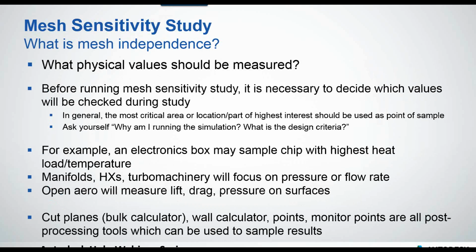All right. So a lot of times people ask me, what should I measure? What's my physical recording that I'm going to use as a reference? And that really is based on what you're doing. A good way to phrase the question is, why are you running the simulation? If it's an electronics package, find the hottest chip or the one with the highest heat load on it. If you're looking at pressure across a pump, that's in your defining flow. That's what you care about, or vice versa.